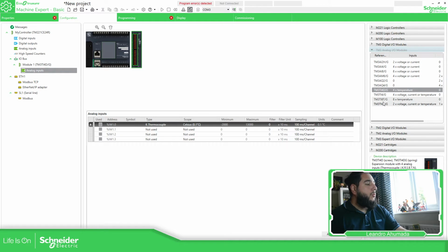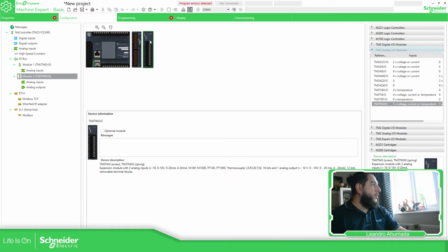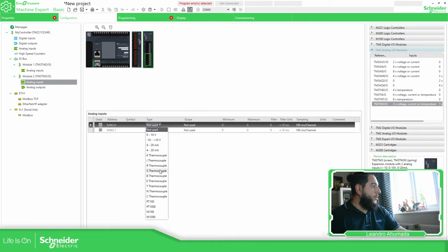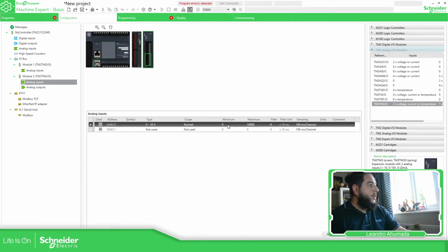But for example, you can use the analog input as a voltage or current, and if you use it that way, probably what you can do is, let's say voltage here, you can scale it or leave it as it is, and then use the conversion just to specify, for example, if this value 0 is going to be, I don't know, 20, and this value is going to be 200. Just to have an idea how you can make the scaling over here.